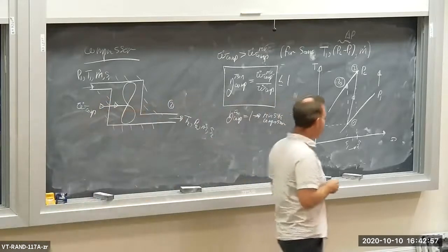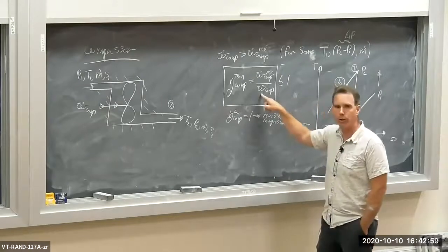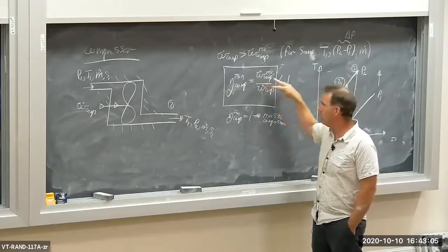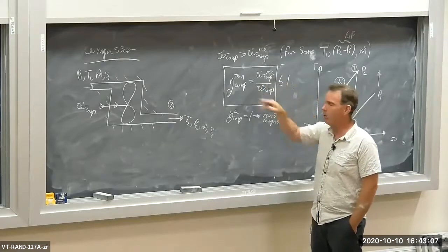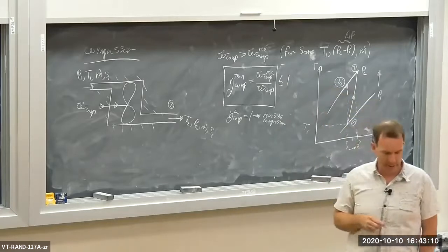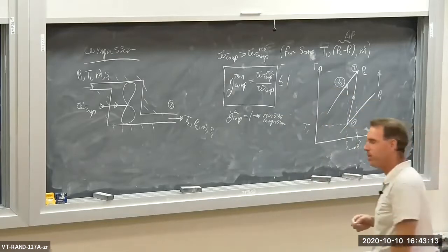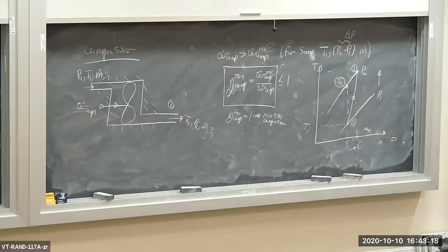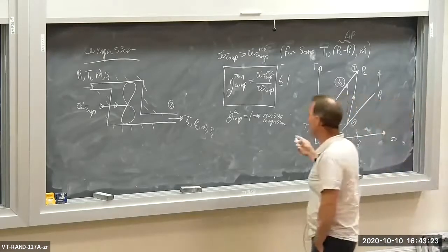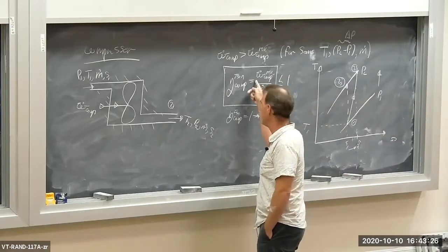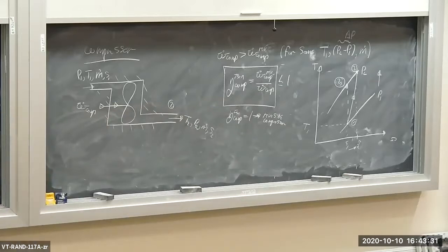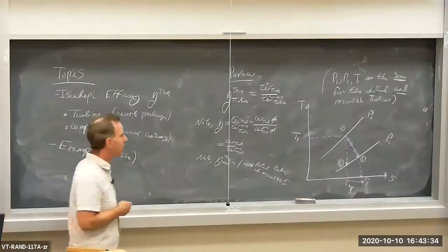The real device consumes the most power to pressurize the flow. The reversible device consumes the least power. So we take the ratio of the two and we call it the isentropic efficiency. If your isentropic efficiency for some device is 1, it necessarily means that the device is a reversible device, a reversible compressor. Isentropic efficiency is the ratio of the compressor work for the reversible compressor to the real work for the actual device. That's for a compressor, and it is the inverse for the turbine.